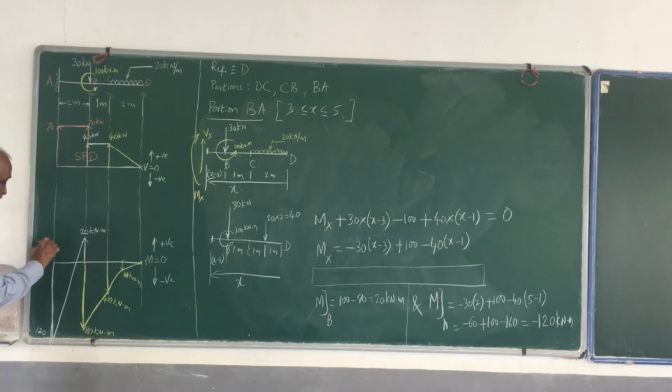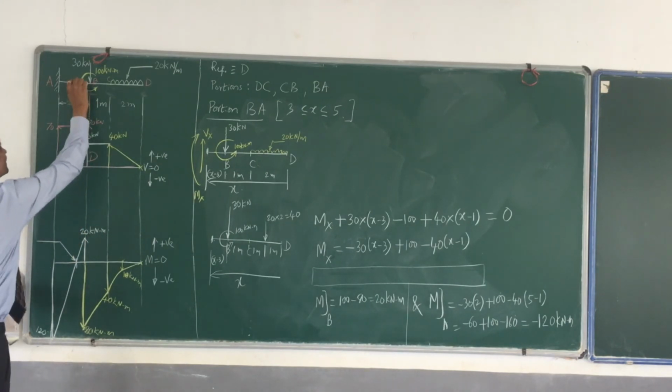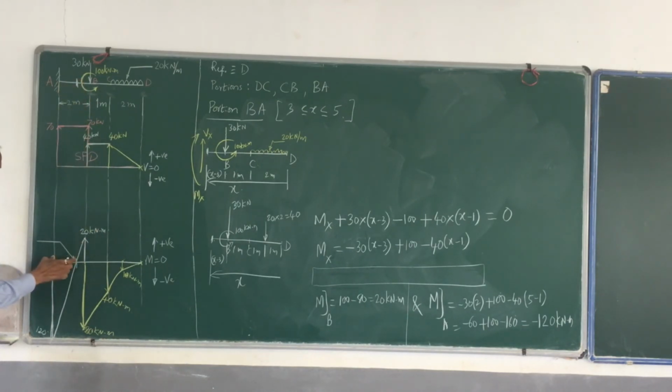Okay, observe this point. Very, very important. This section, you go back here and it's again here, the same distance I am talking about. So this section of the cantilever beam, this side you have positive bending moment, and this side you have negative bending moment.